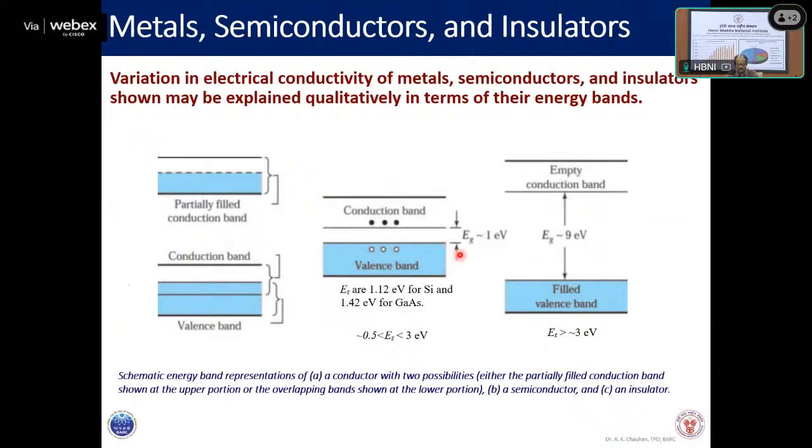Even at room temperature, you will find a certain number of electrons available in the conduction band, and therefore it will give a little conductivity. As you increase the temperature, more and more electrons will reach the conduction band because of thermal excitation. And those electrons already in the conduction band can attain any energy, because all these energies are allowed.